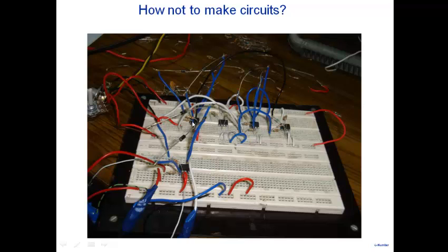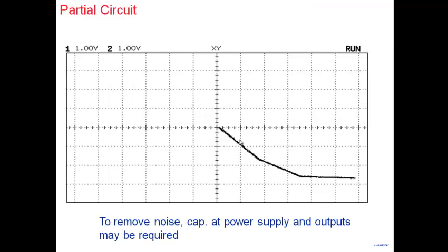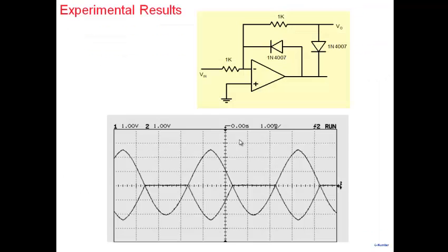So while you're making circuits on the breadboard, the layout is important. Where you run the power line, where you run the ground line, where you take the outputs is important. So besides designing the circuit and simulating it, spend some time and give some thought to how you're going to lay out your circuit, and try to make it as neat as possible. This would help you to debug and complete the experiment in the time allocated. Okay then, as I said, this is a useful circuit, and a fairly easy and interesting circuit. All right.